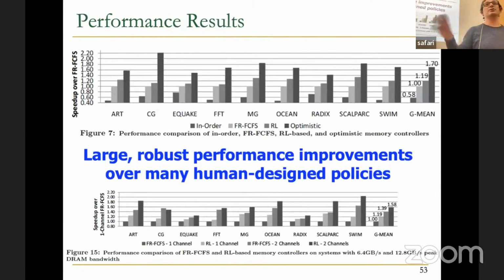No. You really have a hardware, dedicated hardware that does reinforcement learning in the memory controller. Yeah, exactly. There are tables, not terribly large. I think overall 32 kilobytes, but it's really optimized to be built in the memory controller. You can think of this as a hardware accelerator for reinforcement learning built inside the memory controller. Yeah, and I think they are specialized in the sense that they have an exact number of rows like in the hardware accelerator, right? So it won't be very generalizable, right? Yeah, it cannot be generally used by any reinforcement learning mechanism, yes.